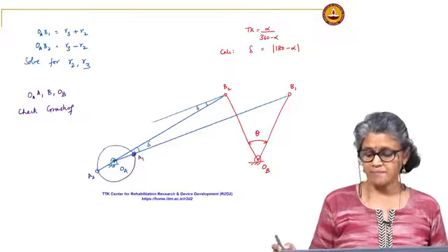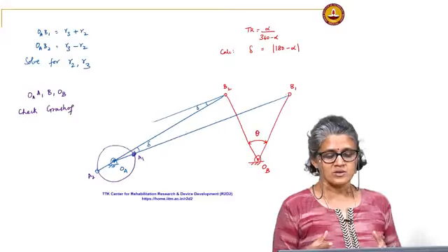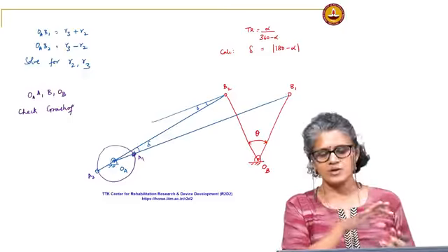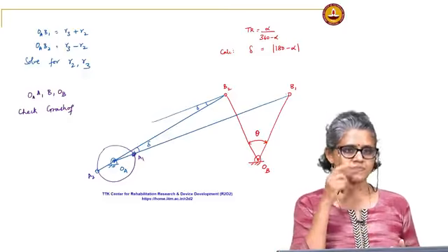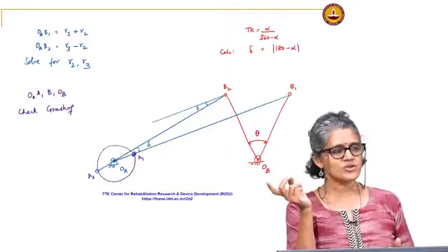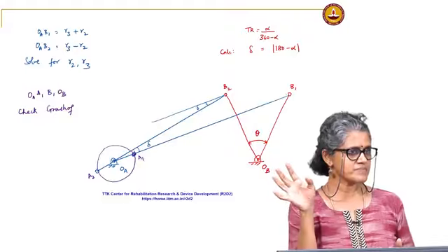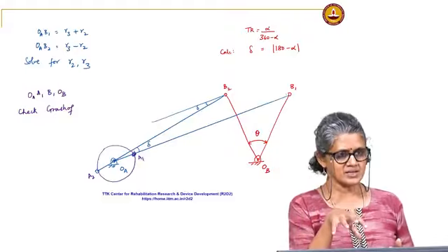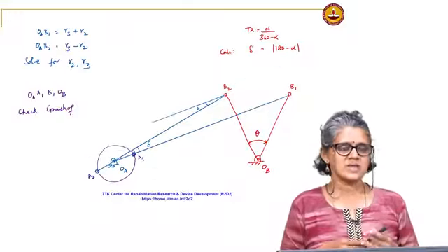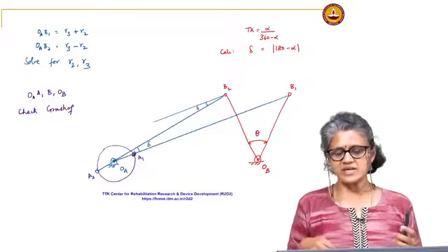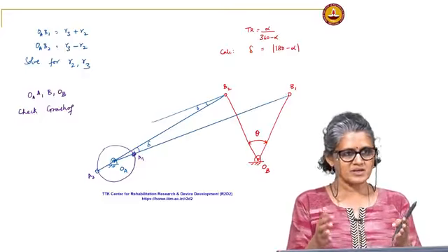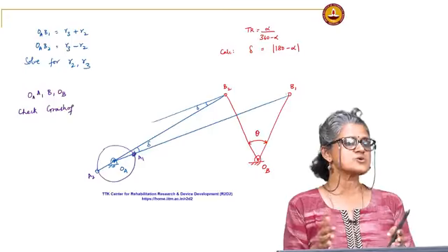Check. So, I was saying, I can scale this entire linkage up or down without affecting any of the angular relationships. I will not affect the time ratio. Okay. So, I can design a crank rocker. I may be designing something for an application where I have really large links, but for my graphical synthesis, I can choose a suitable scale.